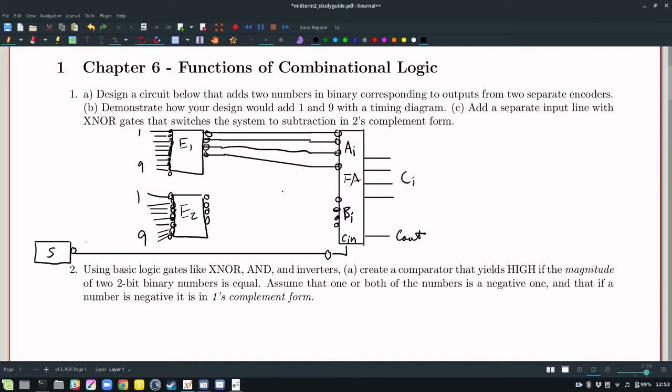So if we have, let's say, an XNOR gate like that, then what we want is for this input to come in like that, and then we're going to peel off that voltage, and then this goes in there. And then we can do a second XNOR gate, connect there. This input comes in here. I need to put my little dots to indicate a connection. And then we have that. And then same story twice more. So I get my third input like that.